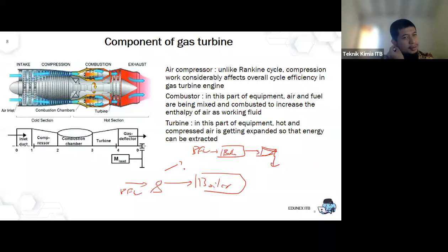Because you can calculate it by using enthalpy at the steam table. This is option number 2, this is option number 1. At option number 1, the energy used to compress boiler feed water from 1 bar to become 40 bars, suppose, is much smaller compared to case number 2. Increasing the pressure of the steam from 1 bar to become 40 bar is much more difficult.